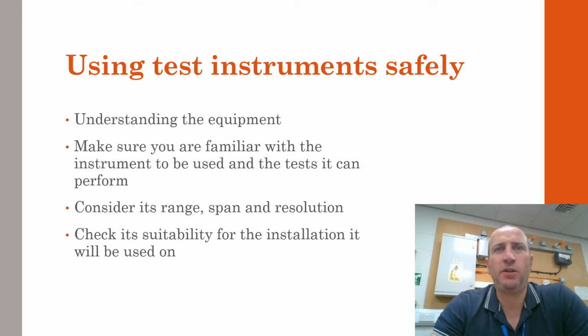This can be a major stumbling block for new electricians when learning about the different methods of testing and fault finding in installations. You must make sure that you are familiar with the instrument to be used, its settings and scales, and the tests it can perform. Consider its range, span, and resolution, and check its suitability for the installation that it will be used on.